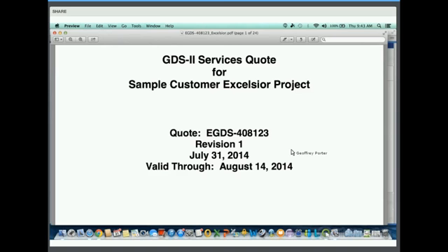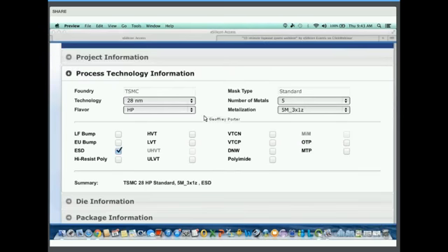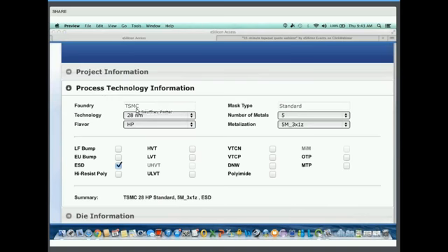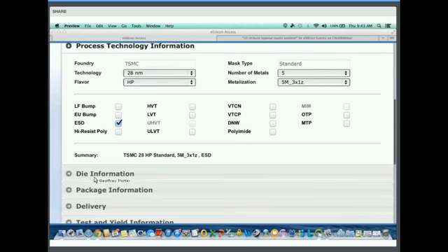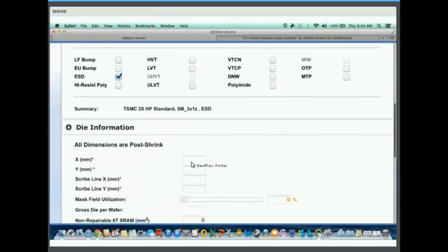Oh, and actually, maybe they were speaking about mask field utilization, so I'll just highlight that. In the process technology nodes where mask field utilization is an issue, because it will drive wafer cost, we will report to the user, for their die size, what the mask field utilization is in the UI. If it's okay with you, Mike, I can just quickly show what I'm speaking about there. Okay. Yeah, we're running to the end of our time limit. I want to try and keep this to 45 minutes, and we're getting to the end of the questions as well. Okay, this will just take 1 second.